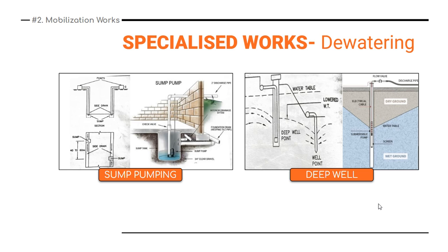Okay, so as we are going for low risk building, sump pumping is quite beneficial, because here what happens is you're going to have a small trench, so that the water via slope comes to a particular sump where you need to dig a big well, and in that well just use a submersible pump and drop the water and throw it outside the plot area, and you will see that your land is out of the stagnant water condition.